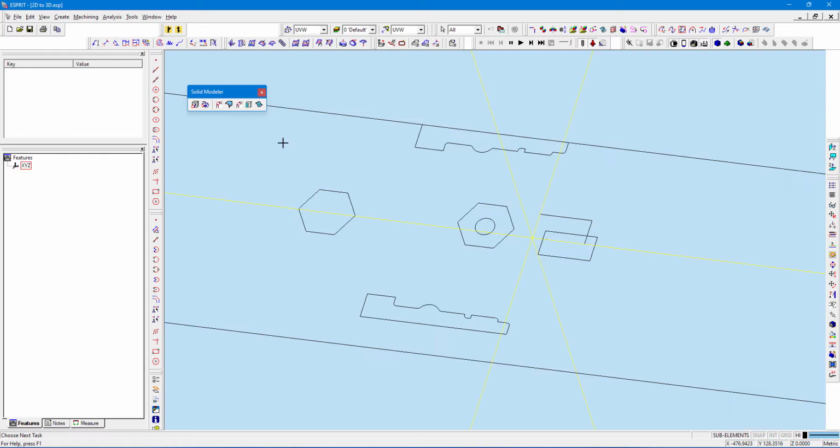In this session, we are going to see about the conversion of two-dimensional to three-dimensional, and in detail about how to do some extrude and revolve options by using solid modeling tools, which is very helpful for designing simple sketches in a CAM program and for successful generation of tool paths. First of all, we will see the extrude tool.